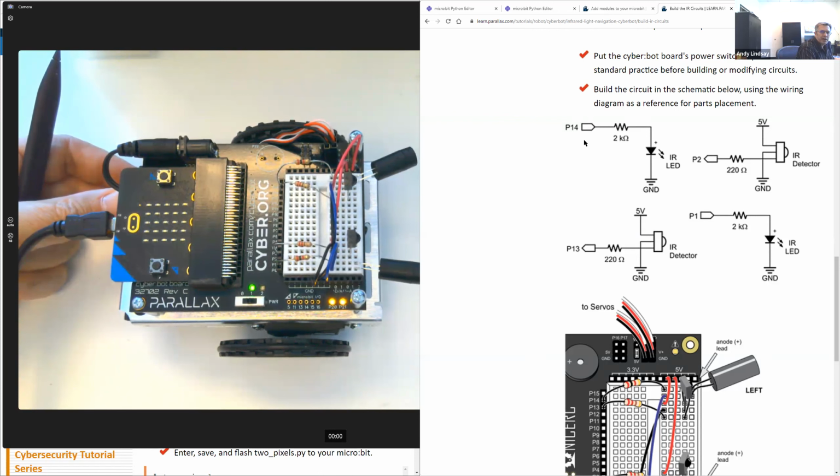So yeah, there's an IO pin, which is going to have rapidly turning on and off signals. And when it turns on, when it applies 3.3 volts here, ground is considered 0 volts. And so there's electrical pressure across the circuit, and current flows through the circuit, and the light comes on. And the resistor resists the flow of current. And so it's there really because it has to be in order to set the brightness of this LED light.